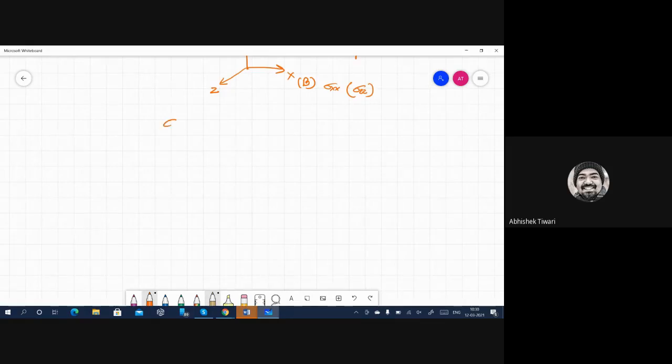And we broke down sigma ij defining like this. So the first term has the stress intensity factor K over root 2 pi r times f of theta. And then there is a second term which is called T stress. I don't know why it is called T stress, but it is called T stress, and it has two components. So the whole matrix is like this.